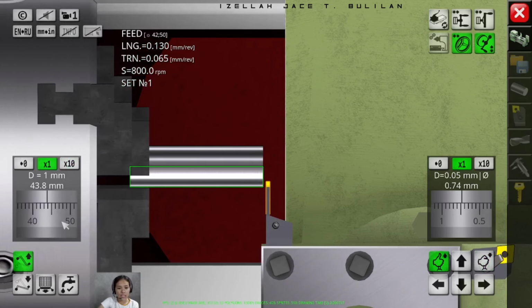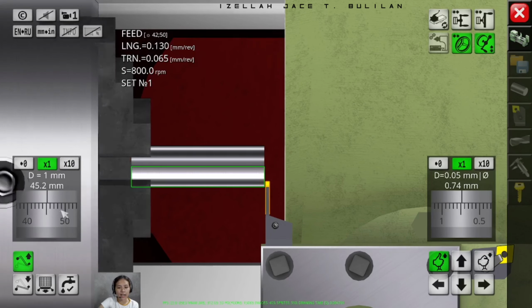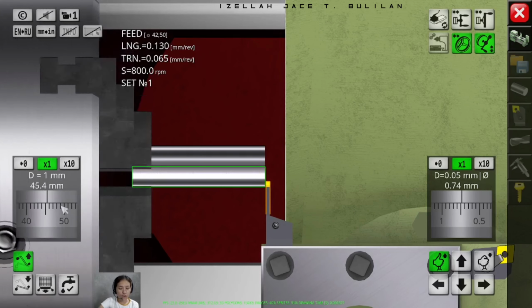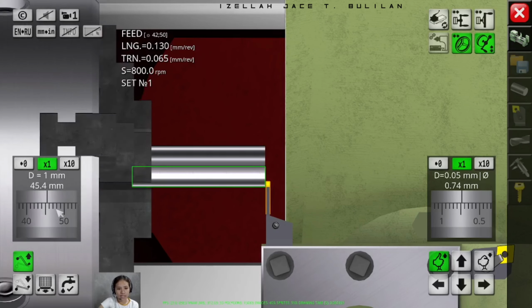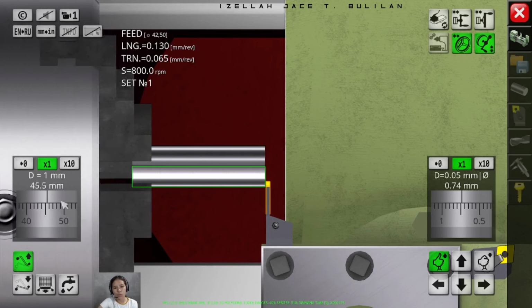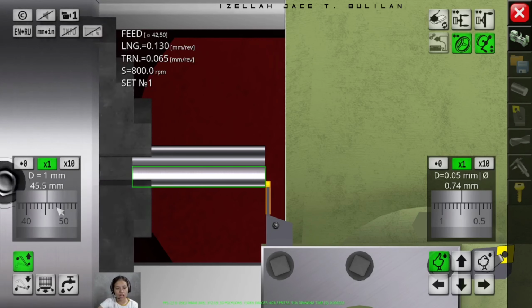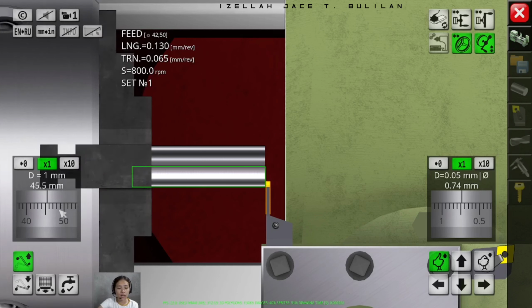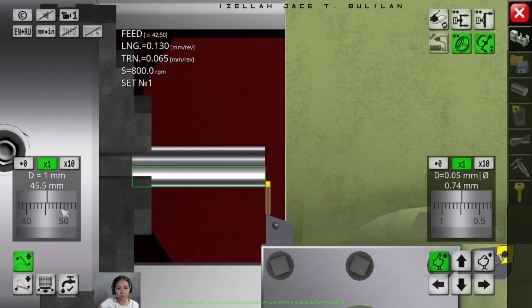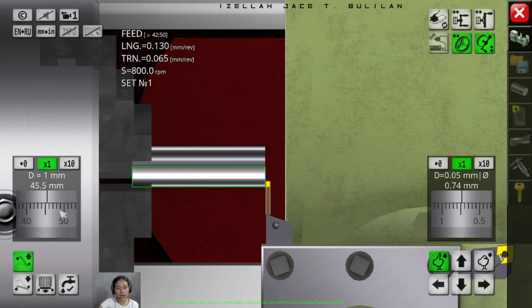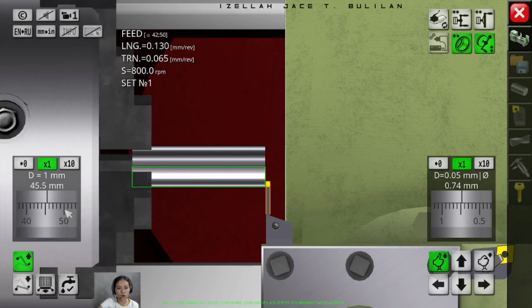The technique that I'll be using is when I calibrate, I'll be using the back portion of my workpiece, because sometimes we do commit errors or mistakes when calibrating. We may accidentally move it into point 1 and that will leave an error to our finished output.